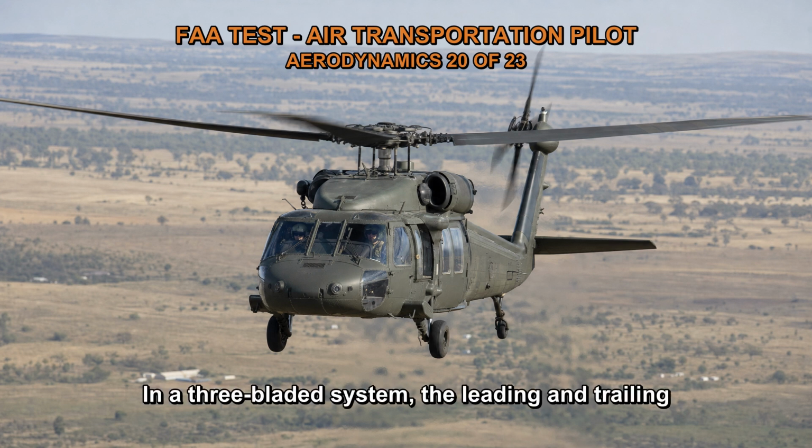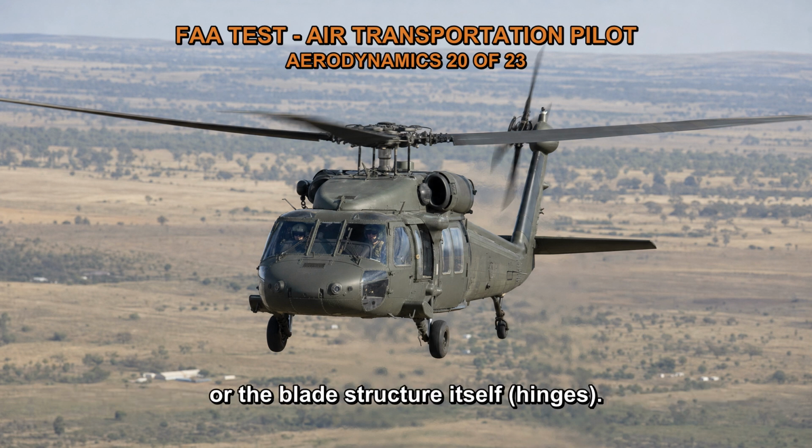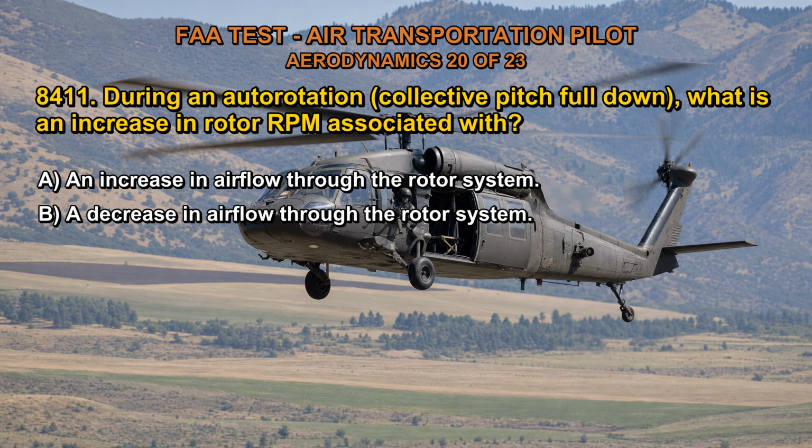In a three-bladed system, the leading and trailing acceleration and deceleration motions are absorbed by dampers or the blade structure itself, hinges. 8411. During an autorotation, collective pitch full down, what is an increase in rotor RPM associated with? A. An increase in airflow through the rotor system. B. A decrease in airflow through the rotor system. C. A decrease in airspeed.